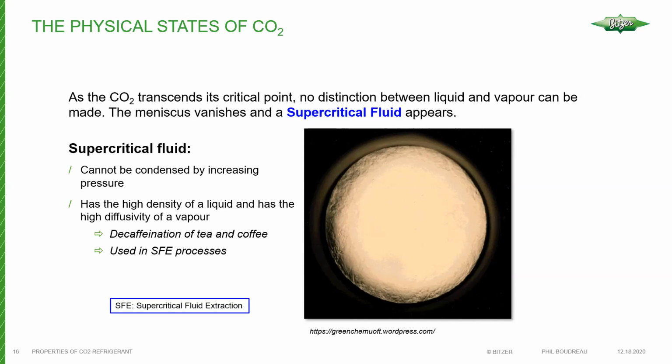Note that unlike other refrigerants we're familiar with, where we're working subcritically, you can't condense liquid. You cannot reform any liquid by increasing the pressure in this case. Once you're above the critical point, we can no longer make liquid by increasing pressure. A very, very interesting set of characteristics about CO2.